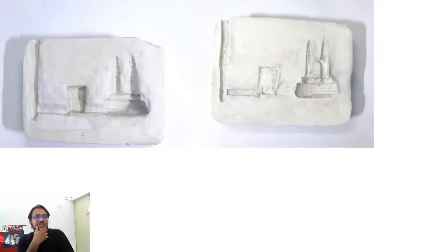Yeah, so this was one of the assignments submitted. The reason I put this here is because there's a mistake in this that I wanted to discuss. All the rest of the casting assignments have the cope and drag pattern, which was on top and the bottom, right? Here he did it side by side. This is a mistake, right? You shouldn't do it like this.